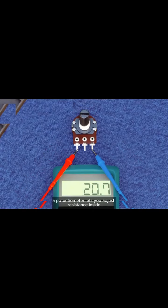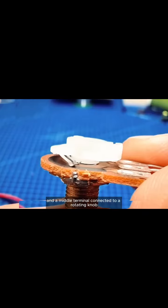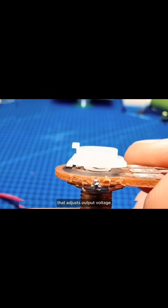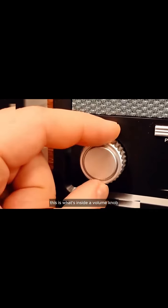For example, a potentiometer lets you adjust resistance. Inside, it has a resistive track with 2 fixed terminals at each end and a middle terminal connected to a rotating knob that adjusts output voltage. As the knob is turned, the position of the sliding contact on the resistive track changes, changing the output voltage. This is what's inside a volume knob.